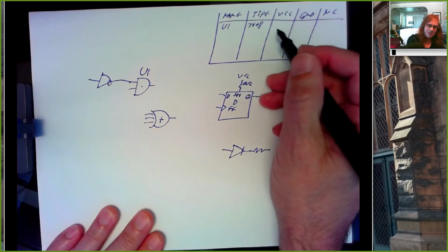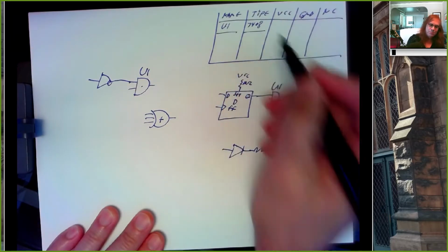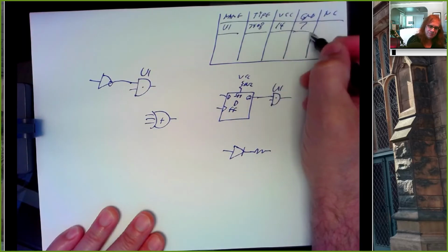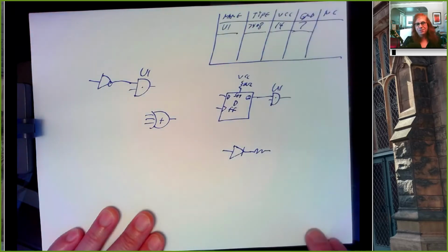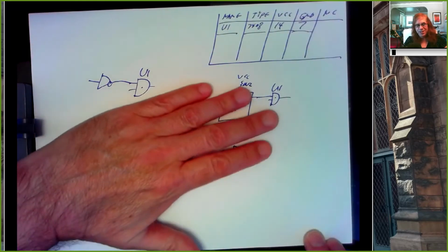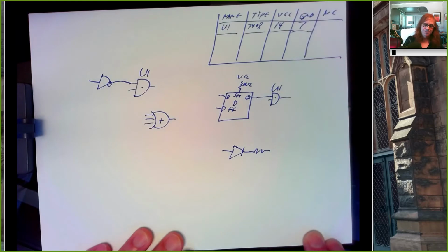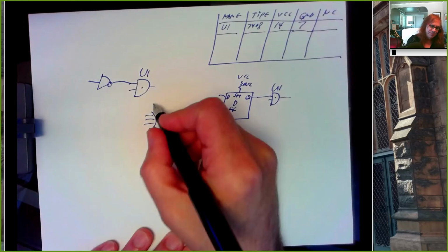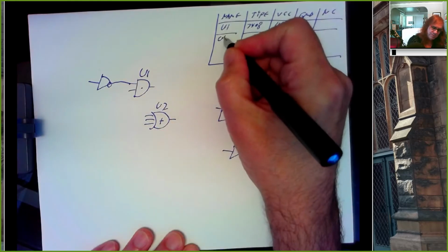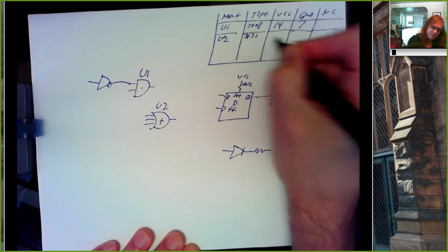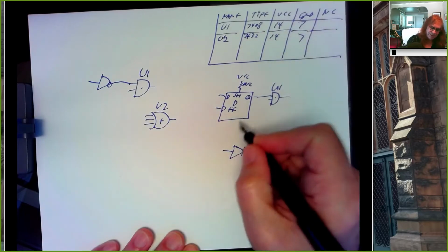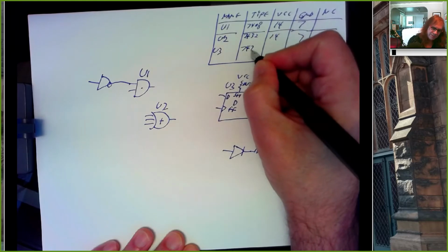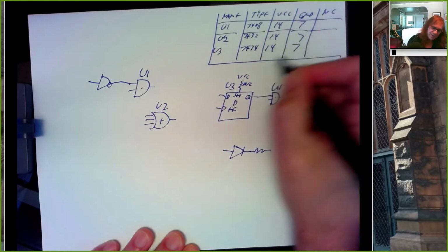This is really saying, here's a chip, that's what type of chip it is. This is where I'm going to connect power. This is where I'm going to connect ground. This is how you hook this chip up, kind of independent of what you're doing with the chip, right? And then no connection, just list which pins don't have anything connected to them. So here's U2, and that's a 7432, I think. And maybe this will be U3, and that's a 7474. And so on.